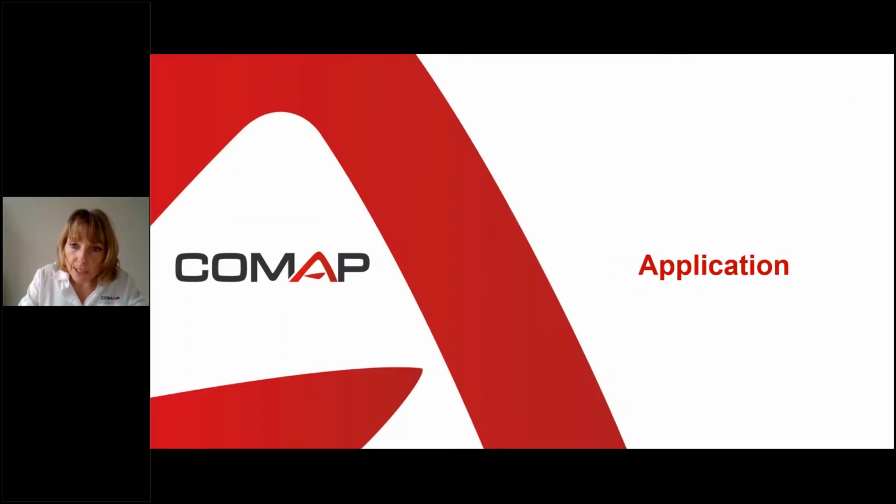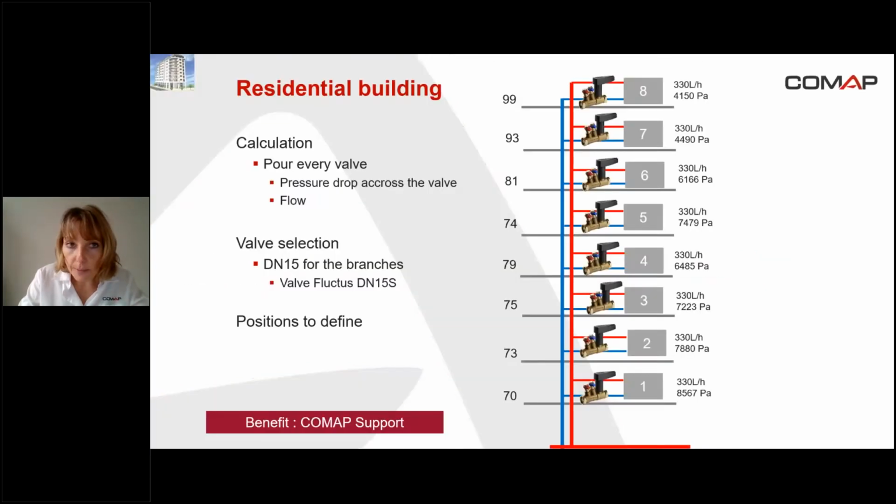An application now. I've just given you all the benefits of the valve. We are going to see now an application. It's still my residential building. In order to install balancing valves, we have to do some calculations. For every valve, it's necessary to know the flow and to calculate the pressure drop across the valve.